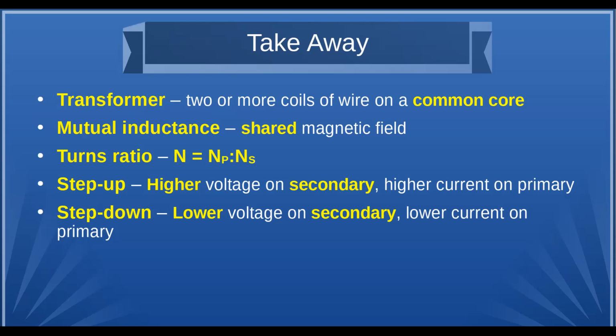Now, later on, we'll talk about impedance of a transformer, which is the square of the turns ratio. So if I had a turns ratio of 2, the impedance ratio is going to be 4. And that will be when we talk about matching for antennas, basically.